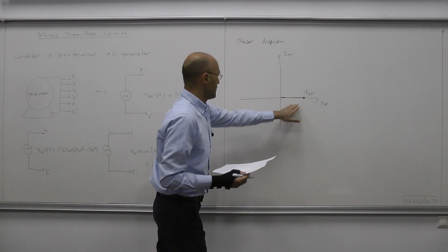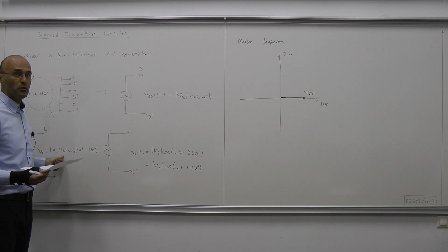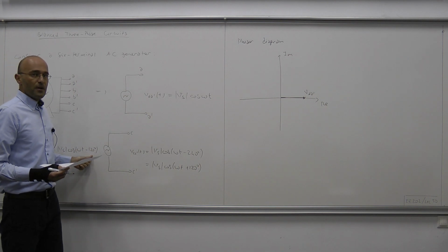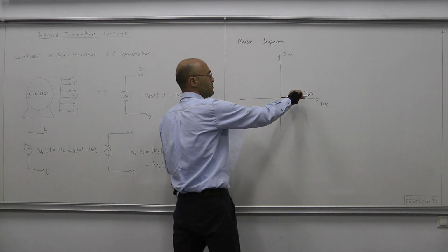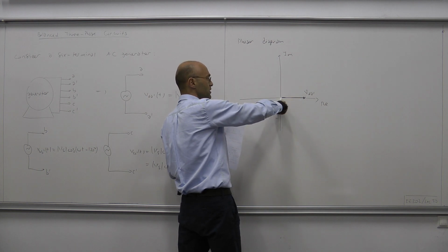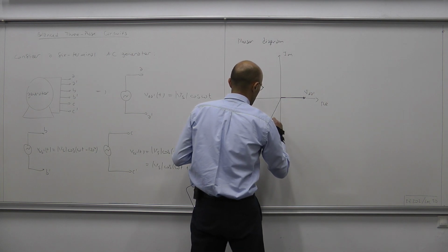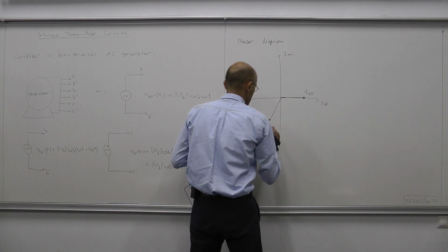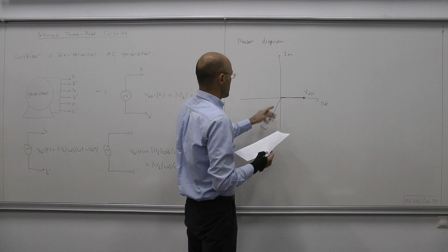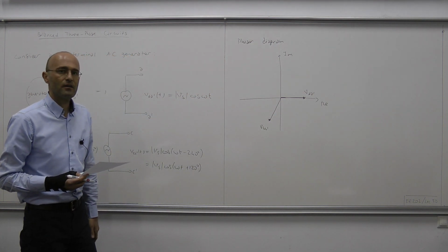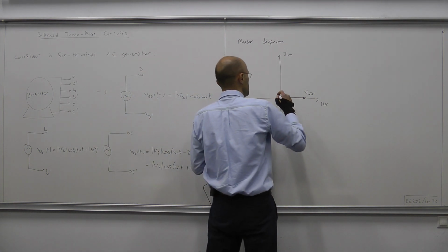And then the phasor for V_BB' has the same magnitude, but the phase is 120 degrees shifted in the counterclockwise direction. So from V_AA', we take this vector and shift it 120 degrees. So that's something like this. Okay, so this is our V_BB', the phasor of this voltage. And finally, from V_BB', we go another 120 degrees and we reach V_CC'.